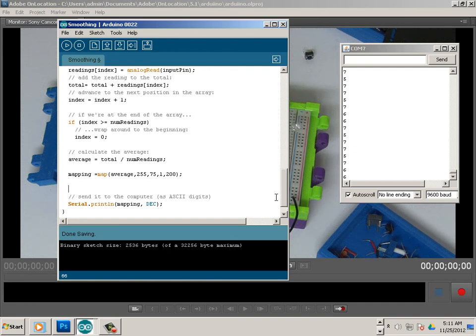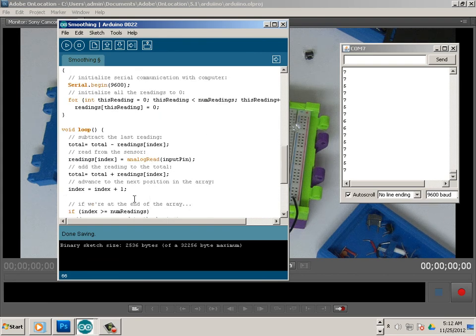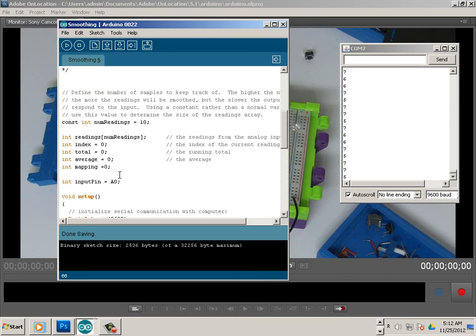Okay, so in this case, we're going to take and paste this over. And just before it gets into the serial print of it, we'll take an analog write to a pin. Well, LED pin, what's that? Well, let's write it up here. LED pin, and in that case it's equal to 9.